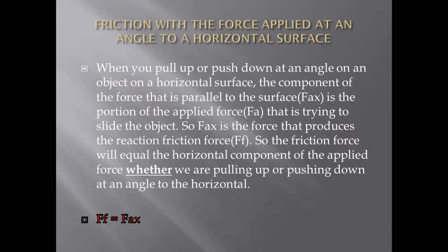When you pull up or push down at an angle on an object on a horizontal surface, the component of the force that is parallel to the surface, FAX, is the portion of the applied force that is trying to slide the object. So FAX is the force that produces the reaction friction force, FF.